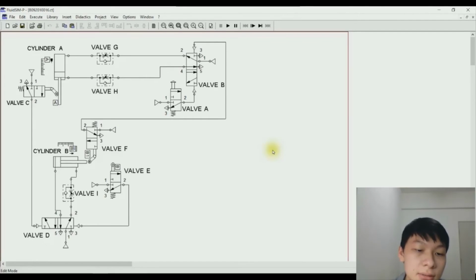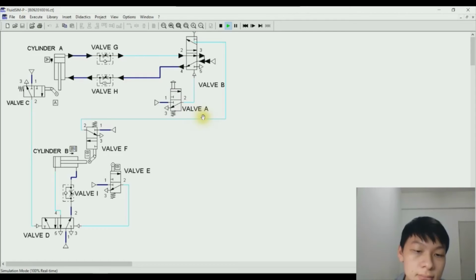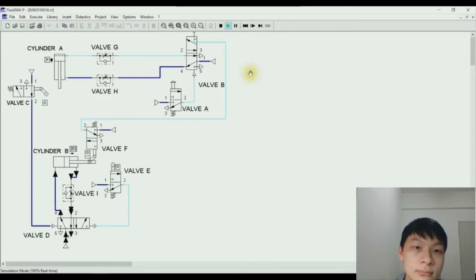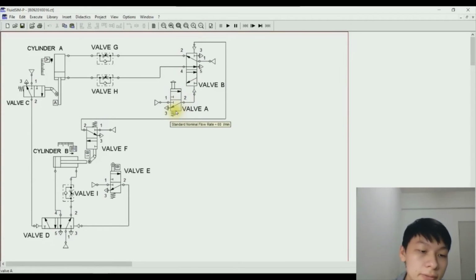This is the design circuit function. Now we start the simulation. This is the start button. After pressing the push button, cylinder A will outstroke. This means the furnace door will rise. Then cylinder B will outstroke to push the object into a tank underneath. Then cylinder A will instroke as soon as possible to reduce heat loss. All the components will go back to their initial position.